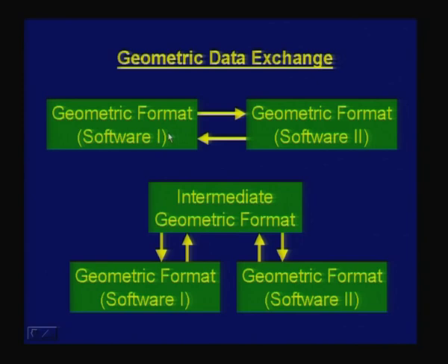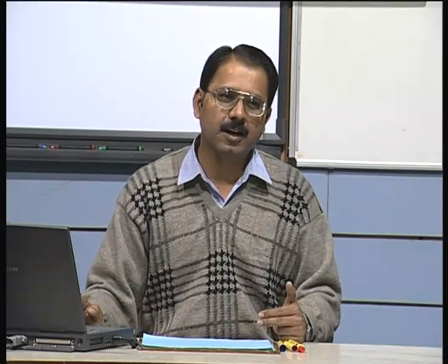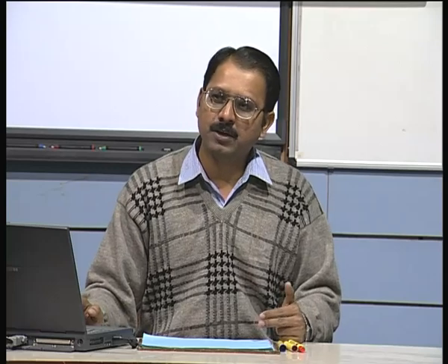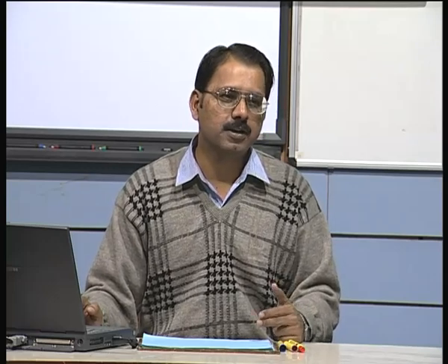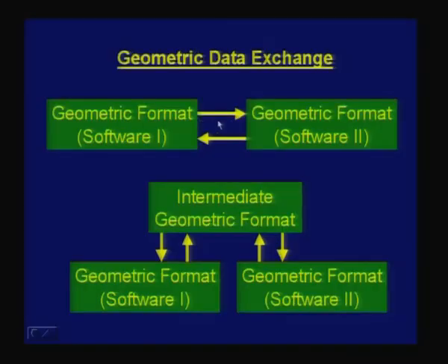Take a simple example of a circular arc, which I think we discussed some time back. If somebody has to represent or store a circular arc, what should be the input? Somebody may say it should be stored by inputting a center point of the arc, start point or end point, radius, start angle, end angle. You may not need all these values. A certain combination of these is enough to store a circular arc uniquely. So, package 1 may store it in some manner, package 2 may store it in some other manner. So, whenever there is this difference, I need to translate.